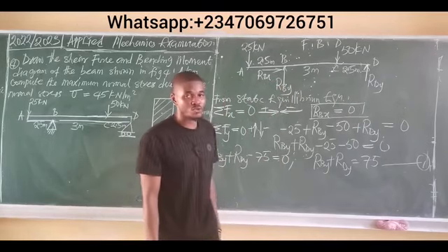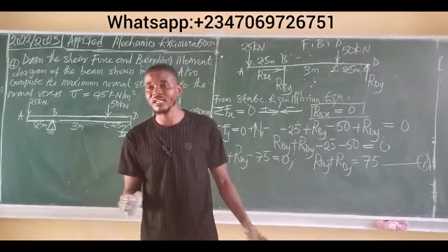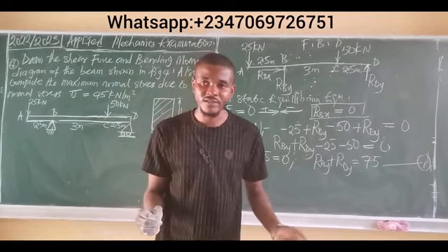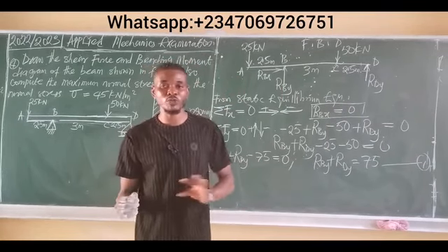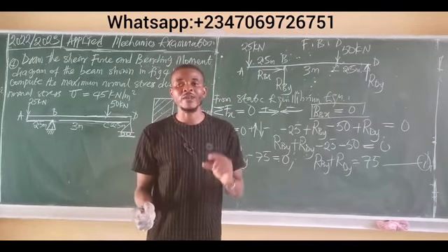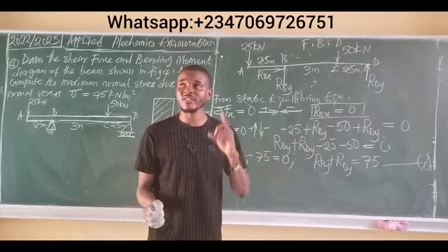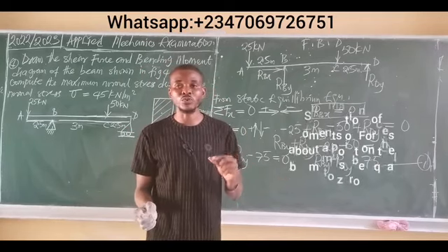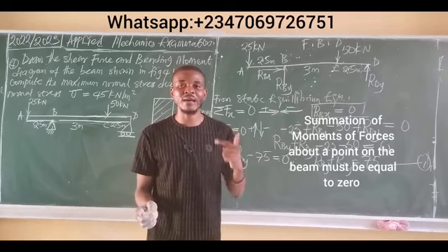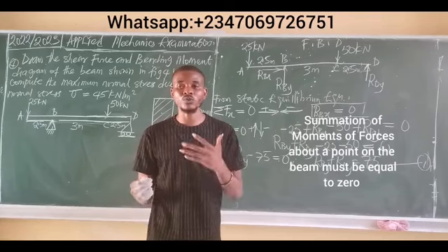We simply call this equation 1 because we have two unknowns in that equation and we cannot find them. Two unknowns in one equation, it is impossible to solve. Now, the only way we can solve this is by considering the third equilibrium law, which is the moment law. Summation of the entire moment acting on the beam is equal to 0.